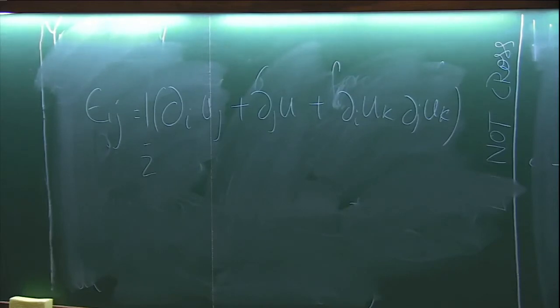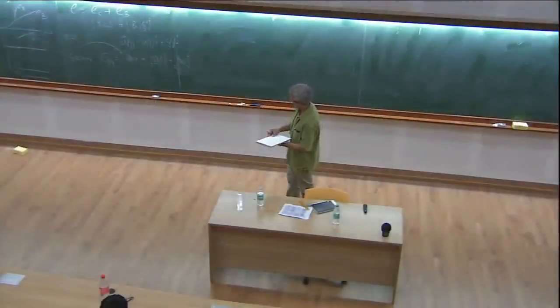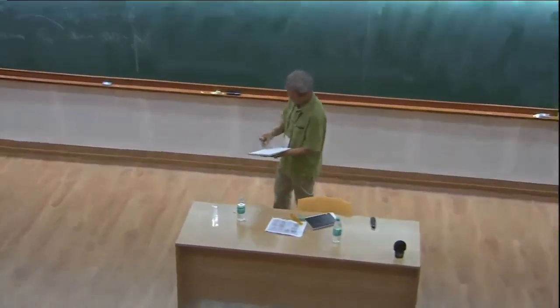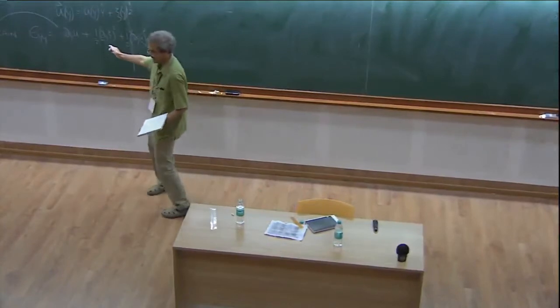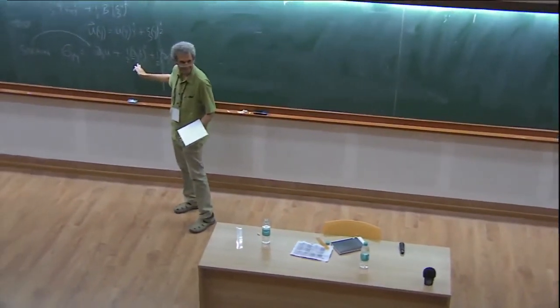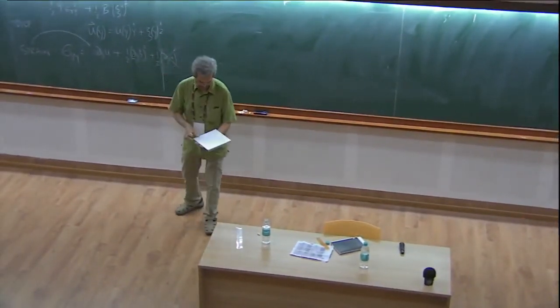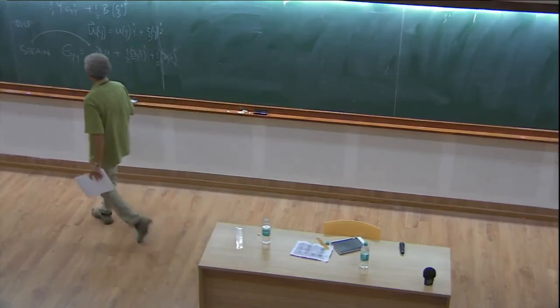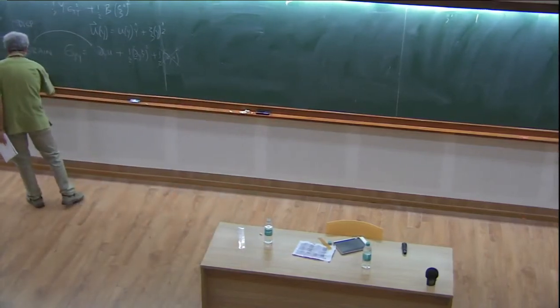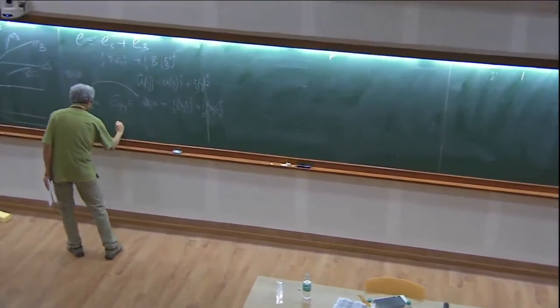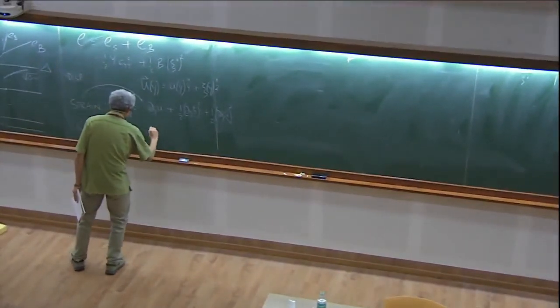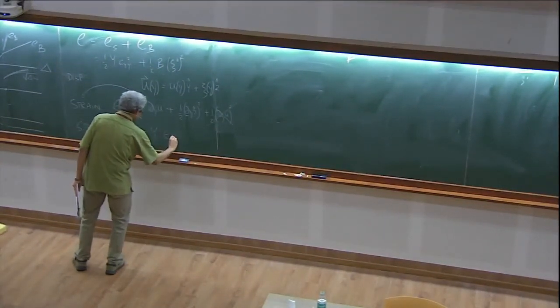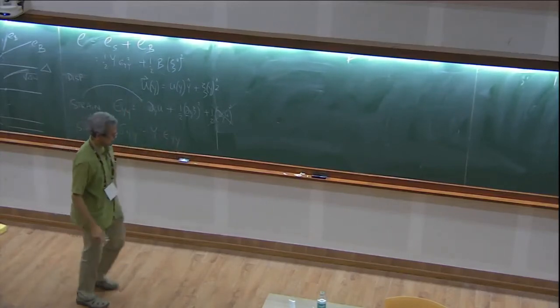You can go ahead and go to town, please yourself, and use that also, but I'm just going to keep the first available term in each one. And you can see I absolutely have to keep this, right? This is all the out-of-plane things. And it came from that nonlinear piece in the strain. Stress is sigma_yy equal to Y times epsilon_yy.